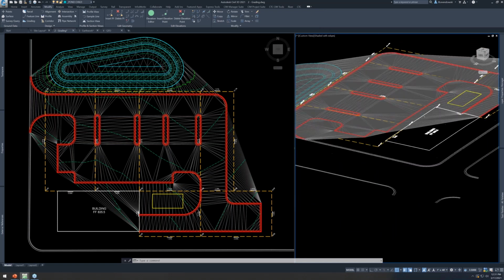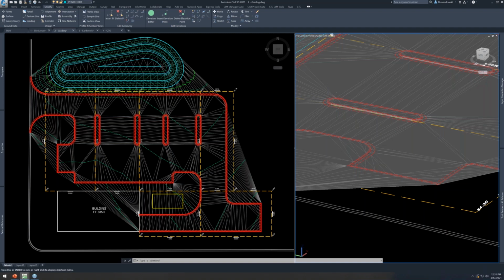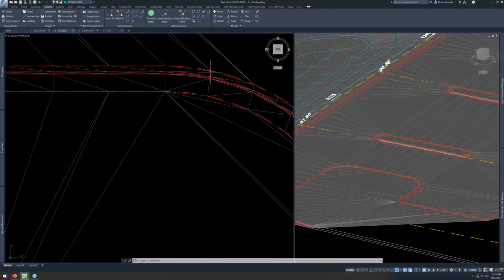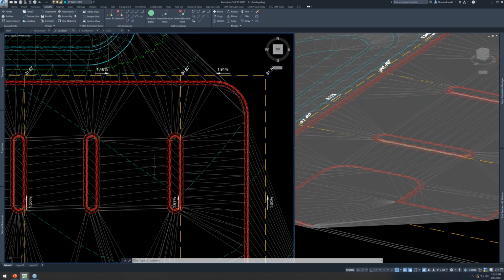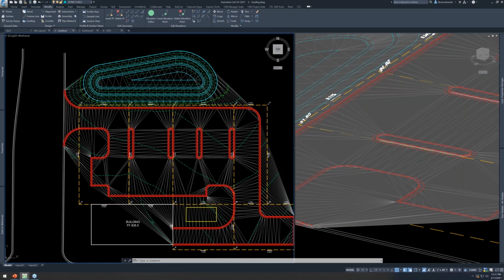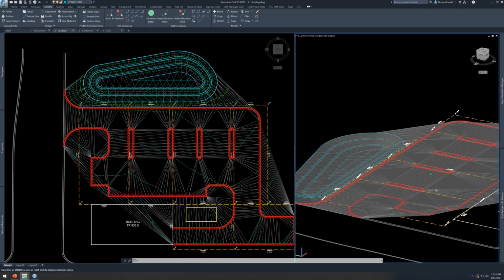Okay. Think about the amount of time it takes to do that stuff, right? Adding break line surfaces, not too bad, but you gotta keep adding stuff as you make new feature lines, right? Or if you gotta go in there and you gotta remove break line sets. Or what about creating all these feature lines in the first place? You're running stepped offset 15 or so times, typing in the values, right? Becomes really tedious, and that's what we're addressing in AutoGrader.